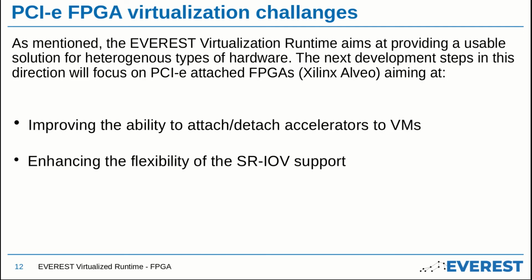In the scope of supporting hardware heterogeneity, our next development effort will focus on another type of FPGA devices. We are talking about the PCI-e attached FPGAs, and we have as a development target the Xilinx Alveo board. Our goals are two-sided. From the one hand, we aim to improve the ability to attach and detach FPGA accelerators to virtual machines. From the other hand, we would like to render the SRIOV support more flexible than it currently is.